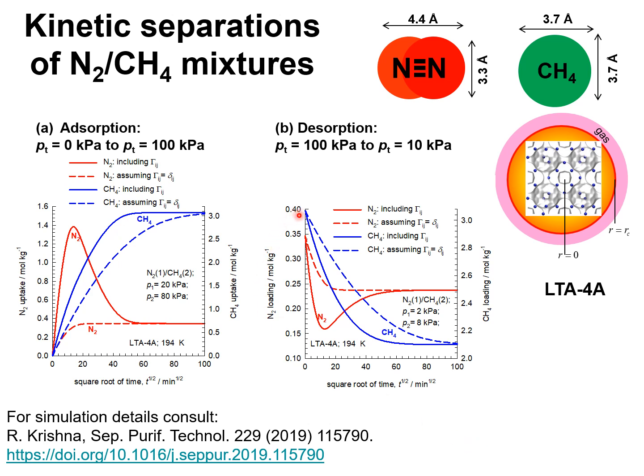The simulation of the desorption kinetics are shown here. Continuous solid lines are the desorption kinetics determined using the Maxwell-Stefan diffusion equation, taking thermodynamic coupling effects into account, and the dashed lines are the simulations in which we ignore thermodynamic coupling effects. We note for desorption that nitrogen experiences a significant undershoot in its approach to thermodynamic equilibrium.